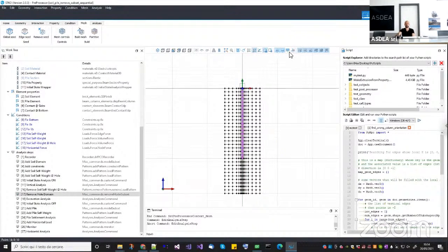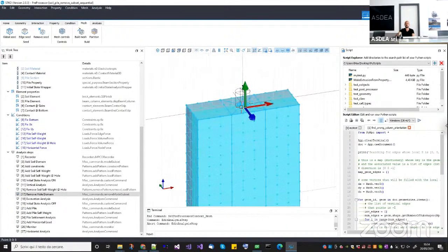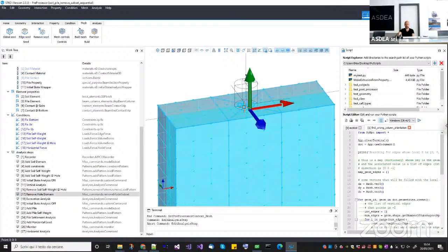Now, to convert this model into a parallel one, you can choose between OpenSeesSP and MP. Unfortunately, I will show you how to do it for OpenSeesSP, but this kind of contact element does not work in OpenSeesSP. So you may ask, why are you showing us how to do the OpenSeesSP command? Because the new contact elements that we added, which I will show you not in the next webinar but the other one, also overcome this problem.